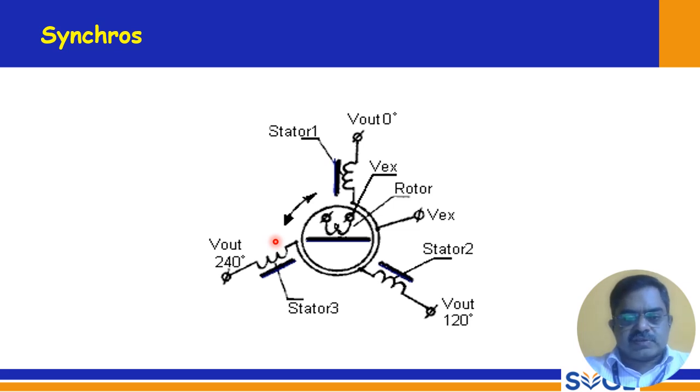The construction is very similar to resolver, and only the angle is increased. Here this is the excitation voltage, and V output is taken from any of these stators, and the input is given to the rotor. That is the simple construction, very similar to our resolver.